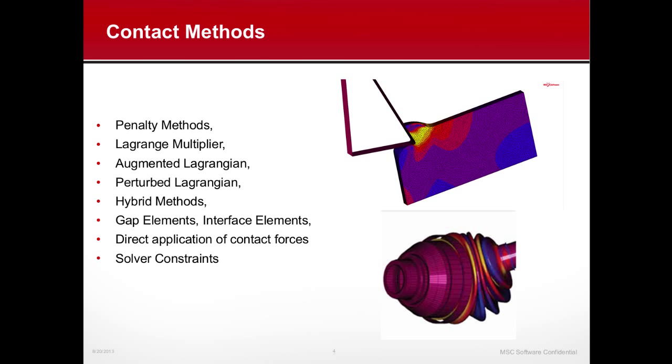And Marc itself does support several of these methods for various contact scenarios. It does support penalty method and Lagrange multipliers, augmented Lagrangian, and solver constraints as well. And depending on the situation, a different method is used.